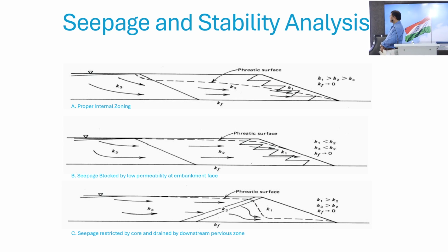But again, we do a lot of control also, because there will be seepage. It's unavoidable because water is there, and these tailings materials also have sand and clay, all these kinds of things that can make a path for the seepage coming down. So we can do some control measures: cut-off trench, slurry wall, grout curtain. Also we put liner, and also we put some extraction wells, mostly on the downstream side.